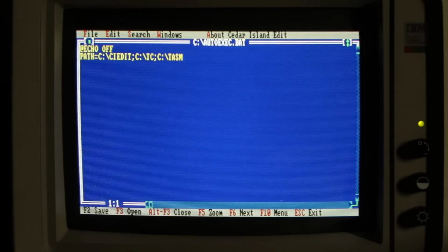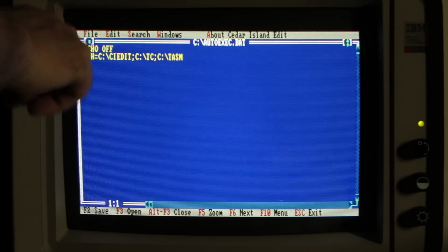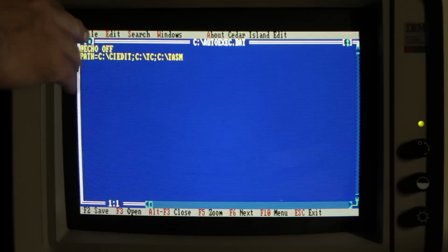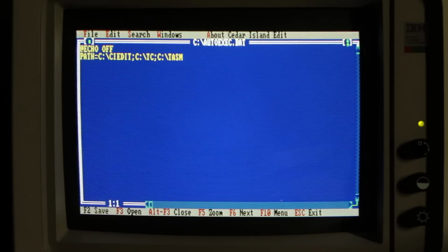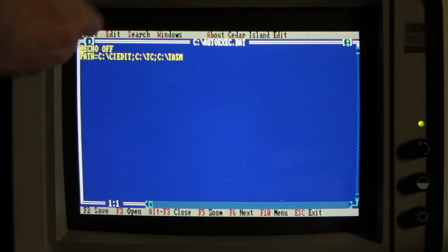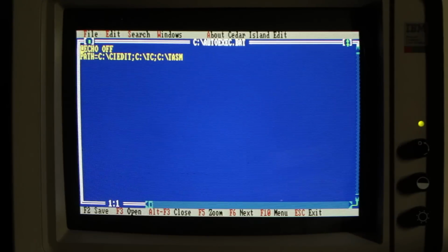They use that row address to select a bank of video memory. So there are 2 separate banks, bank 0 and bank 1. And the row address is used to switch between those. They're just alternating banks all the way down. And so that means that you'll get unique information for each scan line on the screen. Between the character address and the row address, you'll get a different location in video RAM. And so that's how graphics modes work on CGA.